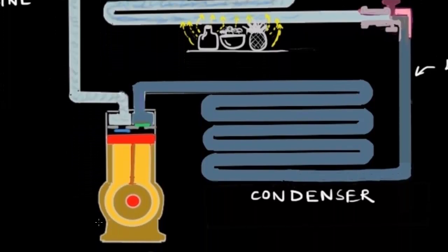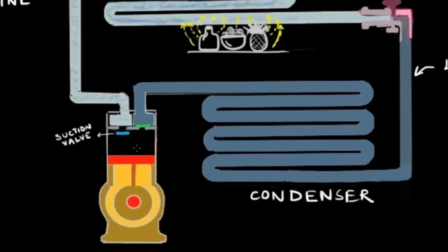So the compressor is a component that's essentially a cylinder with a piston inside. And the piston is driven up and down using an external motor. So the motor provides the mechanical energy for it to go up and down. As the piston is going downwards, it creates sort of a sucking action. It's the same thing that happens when you're trying to draw water or juice from a glass using a straw. You're able to pull the water or the juice into the straw and then into your mouth by basically creating sort of a vacuum inside the straw. So the same thing is happening here.